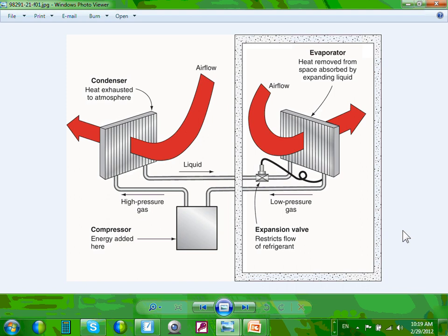The calculation, Chris, we will do calculations on multiples. If you have multiple compressors on one feeder, you have to take the rated load amps, add them up, and multiply by 1.15. All these calculations, you guys will do a few of them next quarter.